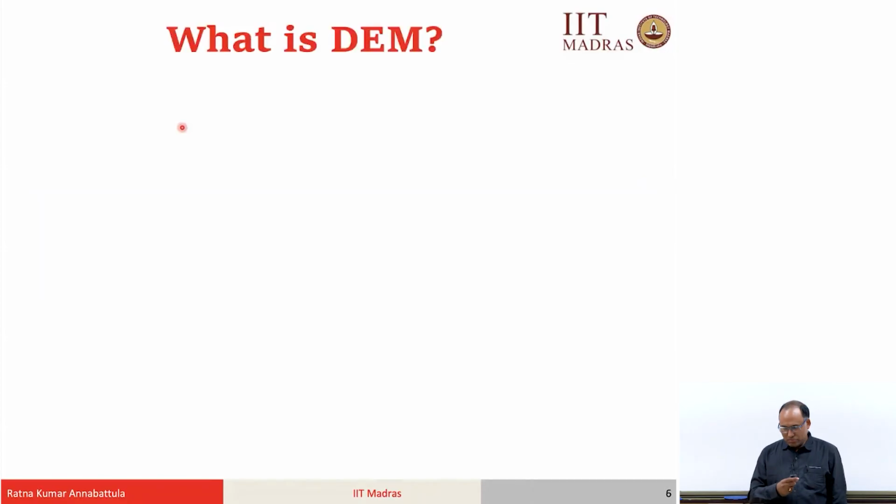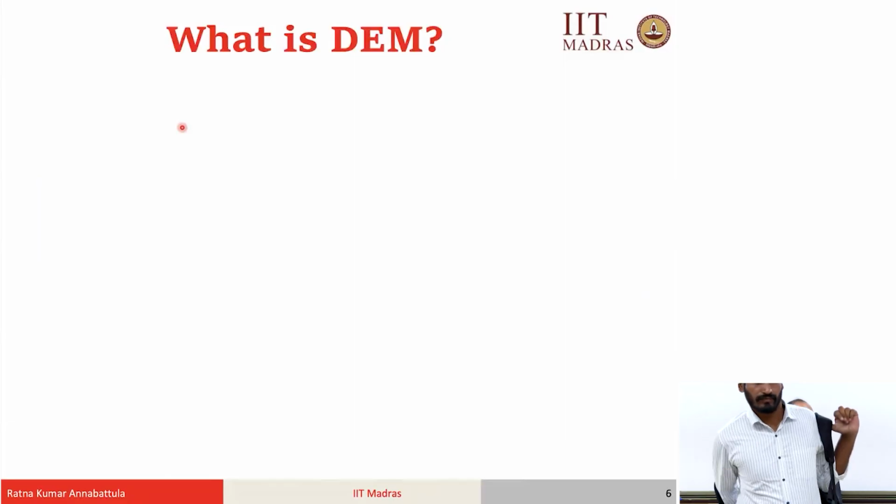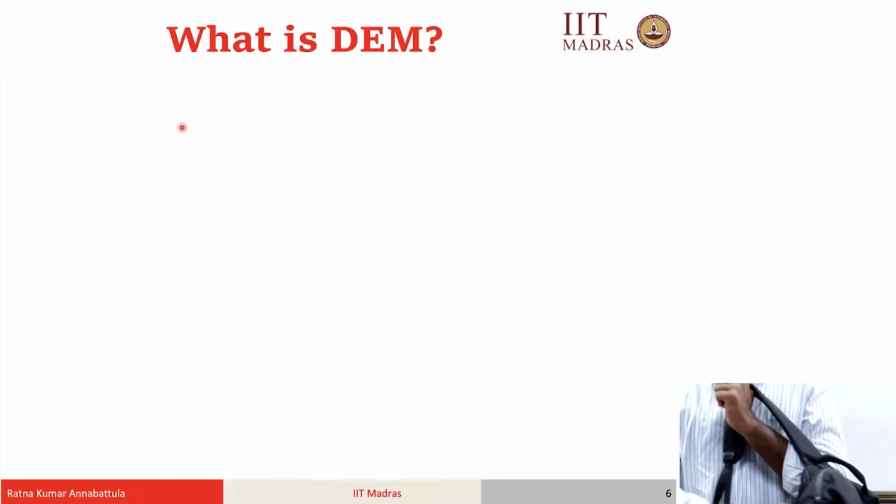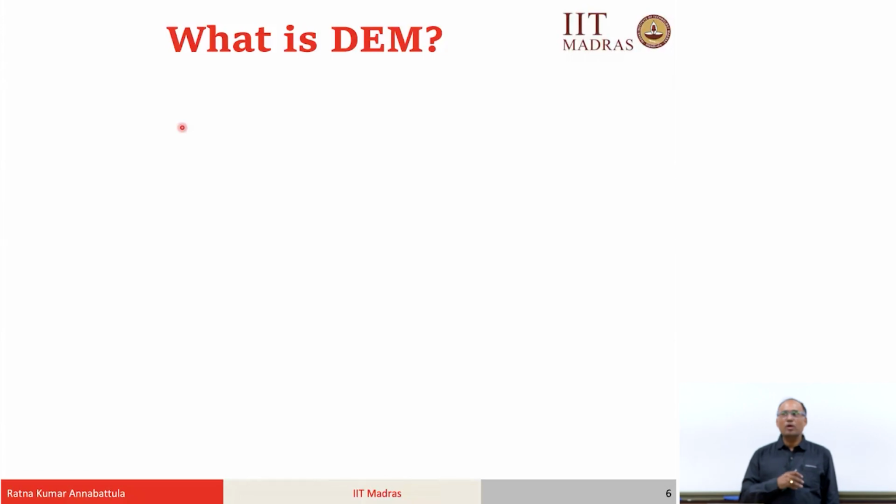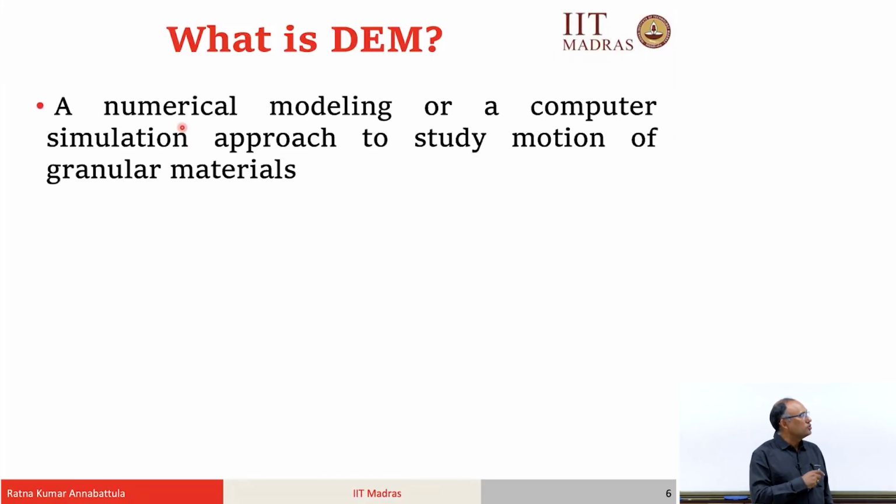So, as I discussed yesterday, the DEM, the discrete element method, is one of the popular techniques to simulate the behavior of granular material. So, what is DEM? It is simply a numerical modeling or a computer simulation approach to study the motion of granular materials or study the motion of a collection of particles. That is what DEM means. It is simply a numerical technique.